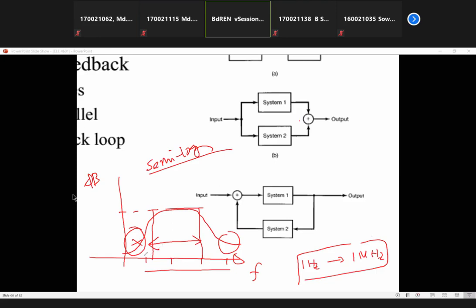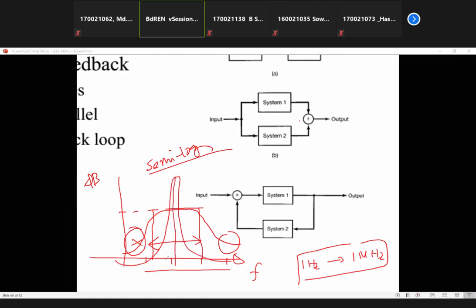But if we have an oscillator, you see that the frequency response curve will be something like this, okay? Theoretically, you will have a frequency F0, the oscillating frequency, and your bandwidth is almost 0. If your bandwidth is 0, then what will be the thing? Eventually the gain of your amplifier needs to become infinite, okay? And your feedback should have positive values, positive feedback. Otherwise, what we are calling an oscillator cannot be designed.